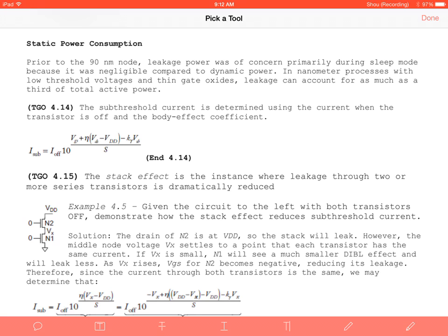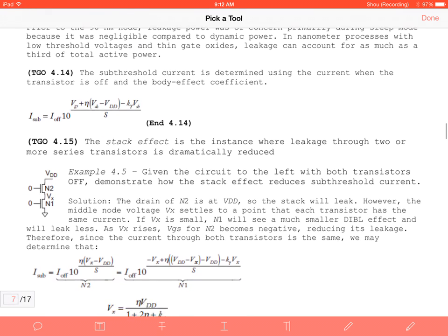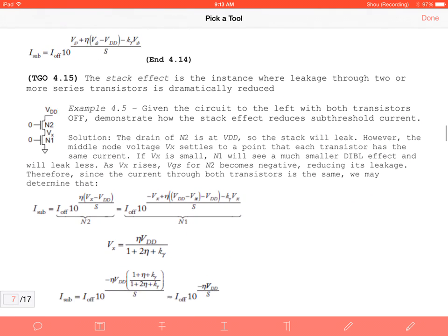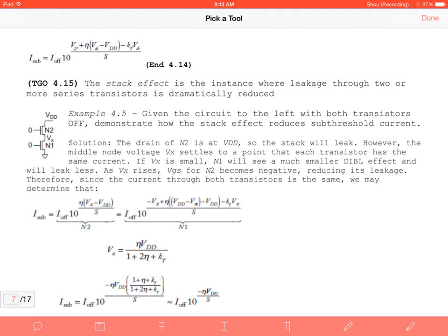So the first thing that's new, example 4.5, is an example question where we are given two NMOS transistors in series, and they're tied to VDD. Now, what is the issue with tying VDD to an NMOS transistor? We just have some sort of VX on output. What's the issue? Passes a weak one. Passes a weak one. That's exactly right.